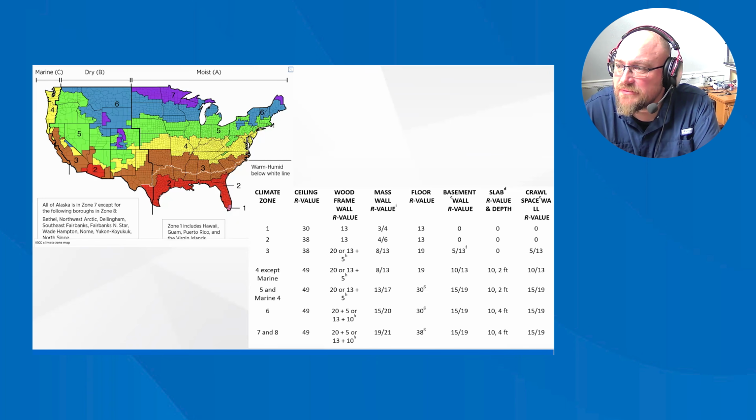If you observe insulation materials used in layers, such as framing cavity insulation and insulated sheathing, the material can be summed to compute the component R value. Climate zones are used to determine applicable requirements in home energy efficiency design and construction. The basement walls, exterior walls, floors, roof, and any other building elements that enclose conditioned space or provide a boundary between conditioned space and unconditioned space are called the building thermal envelope.